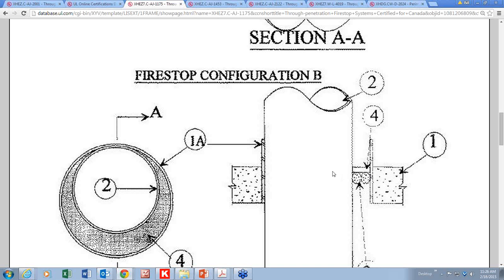I don't know, but there's something in the fire dynamics that said that they have to install the sealant at the floor assembly. That means somebody has to get a sealant tube, a caulk gun that has a long tube, install the backer rod or mineral wool, and then install the Firestop sealant down here, and then tool it smooth so that it winds up just perfect. Great question. Thank you very much for asking.